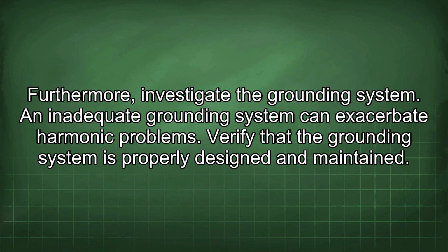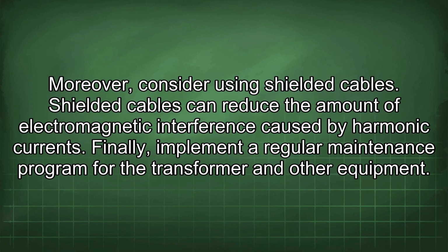Furthermore, investigate the grounding system. An inadequate grounding system can exacerbate harmonic problems. Verify that the grounding system is properly designed and maintained. Moreover, consider using shielded cables. Shielded cables can reduce the amount of electromagnetic interference caused by harmonic current.